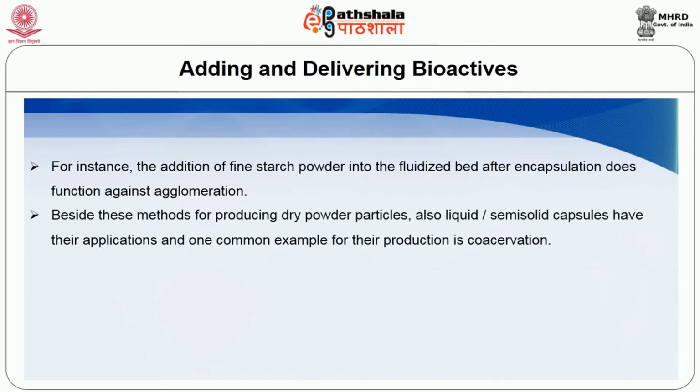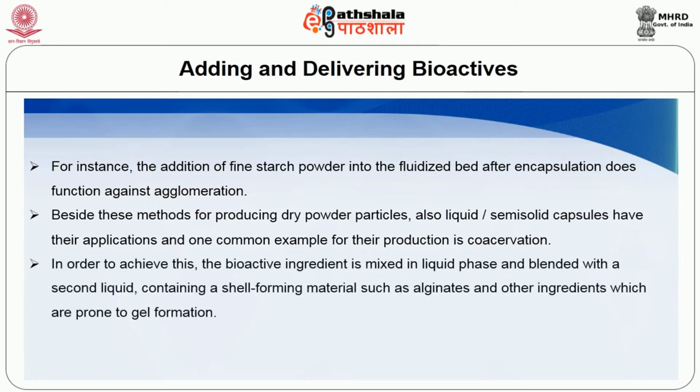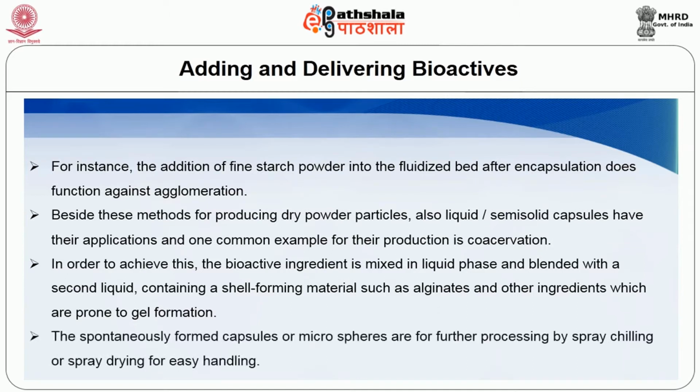Besides these methods for producing dry powder particles, liquid and semi-solid capsules also have their applications, and one common example for their production is coacervation. In order to achieve this, the bioactive ingredient is mixed in liquid phase and blended with a second liquid containing a shell forming material such as alginates and other ingredients which are prone to gel formation. The spontaneously formed capsules or microspheres are processed further by spray chilling or spray drying for easy handling.